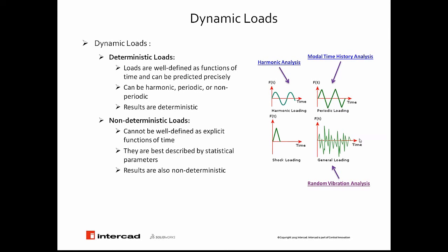One thing in particular, which is the focus of today's webinar, is shock loading. The peak response of the structure to this loading is very important for us. That's why we take a response spectrum analysis, which is well documented to be pretty quick and beneficial for earthquake analysis in our system.